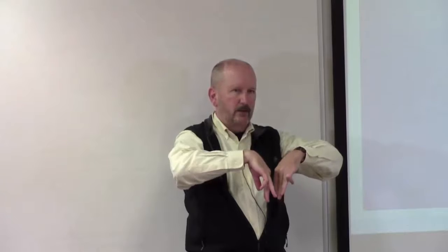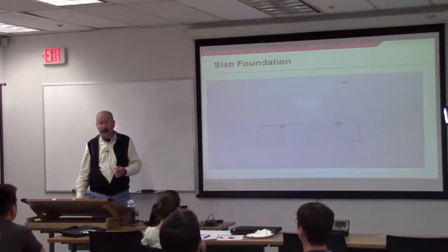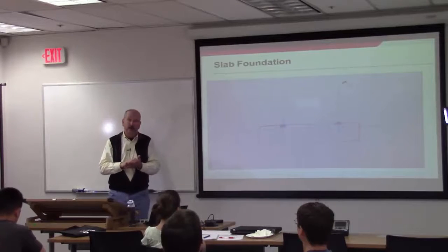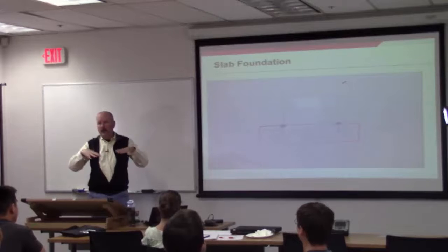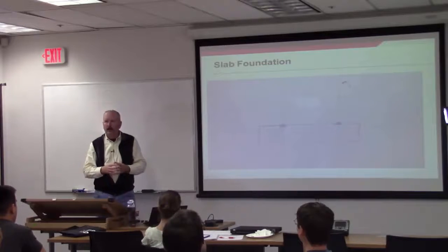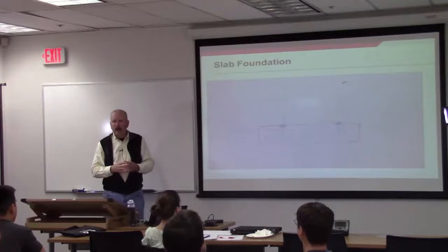But on the surface, it looks normal because you've got these piles sticking out of the ground, and you pour what's called a pile cap on it. That's how you connect those piles that may be steel, they could be concrete, they could be wood. Wood doesn't deteriorate under those, where there's no oxygen there. There's all sorts of things over time that people have used for this purpose. But anyway, you then pour a cap on top of it, connect your anchor bolts in, and it really doesn't look any different from anything else. Now, during an earthquake, it's going to be really an odd thing to watch because ideally those foundations on the piles will not move while everything else liquefies, and it's kind of hard to imagine what it's going to end up looking like. Any comments on that?